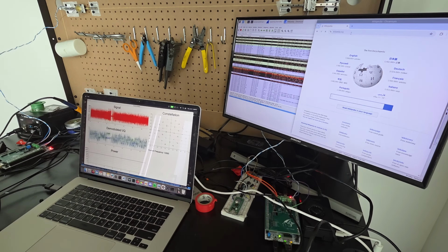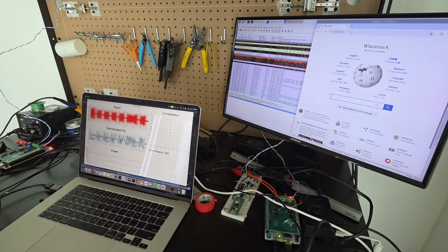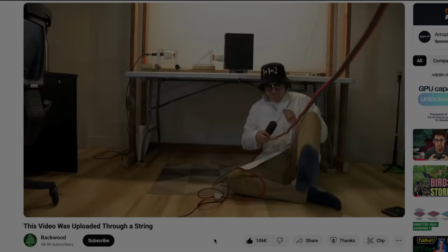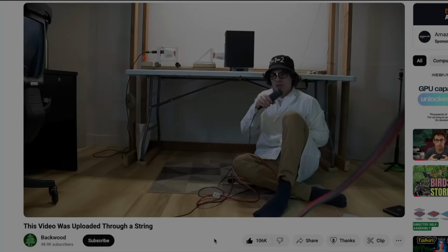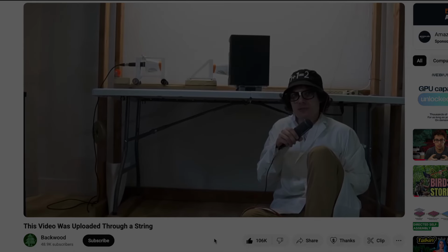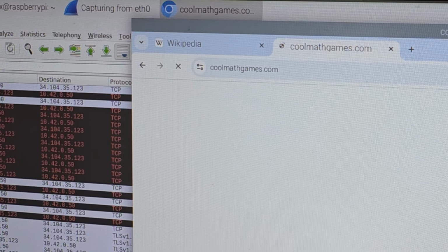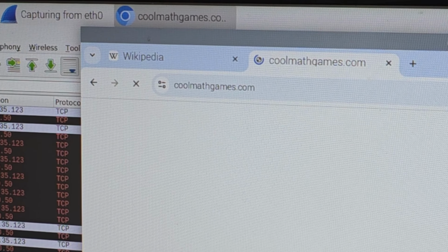And just so you're aware, the connection sounds this bad. And unlike certain other attempts at data over string, we're not going for 5 bytes per second. We're going all the way. 12 kilobits per second. Full duplex 16 carrier orthogonal frequency division multiplex trellis coded 32 QAM.